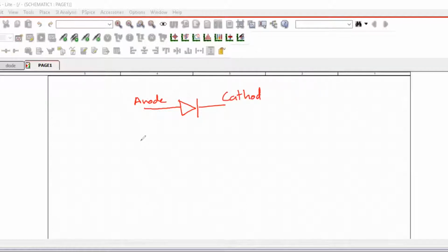When you physically look at the diode, for most diodes we have a cylindrical shape, and then there is a line. That line basically represents this line, and that is the cathode. Since we are talking about a junction diode, it's a PN junction. This is how it works. Now in this activity, what we are trying to do is see how voltage and current behave across a junction diode. So that is what we are going to see.